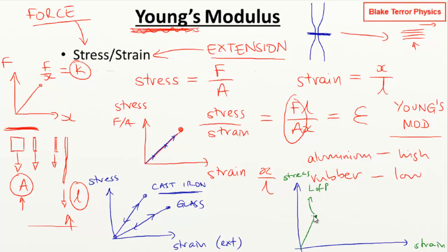Beyond that, it's no longer a straight line. Sometimes you can get a little bit of give before you actually get beyond the elastic limit. So you haven't varied much from a straight line. Sometimes, separate from the limit of proportionality, you get an elastic limit where it will return back to its initial position once it's become slightly non-Hookean. And then after that, you can get some interesting shapes.